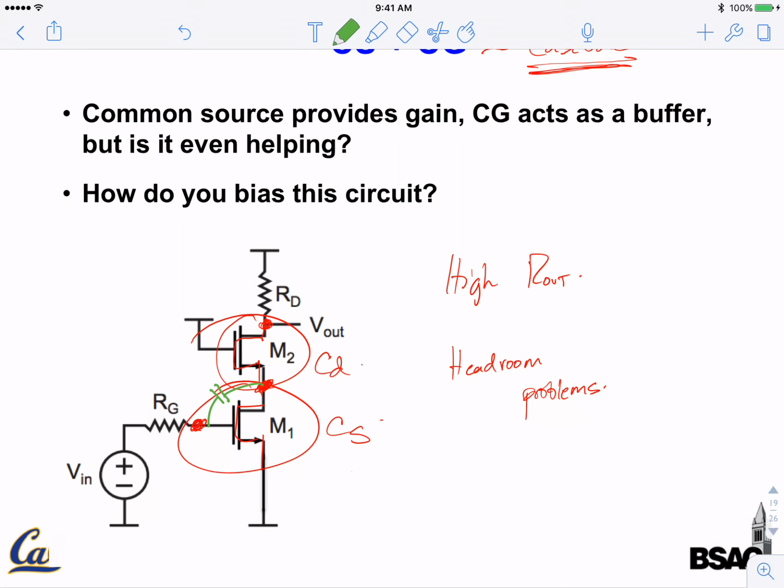For the second stage, we normally don't consider the source and drain to have a big capacitance, so the second stage does not have a big Miller capacitance. But the first stage could have a big Miller capacitance, the CGD here. For this class, we simplify to consider only CGD and CGS. These are the dominant effects. There are many other smaller capacitances, and we just ignore them, okay?